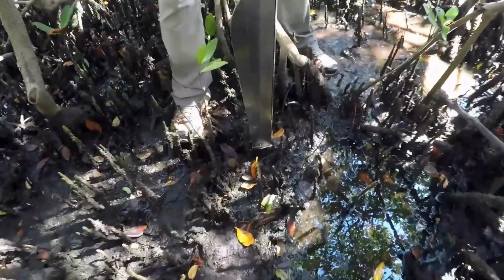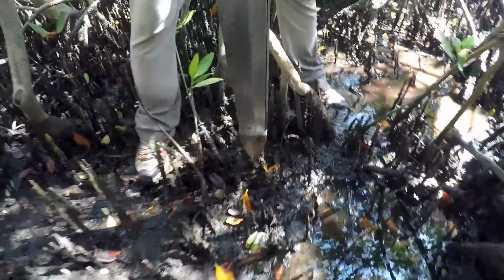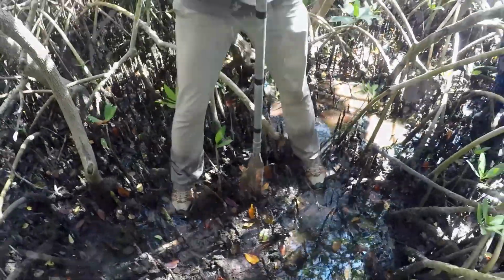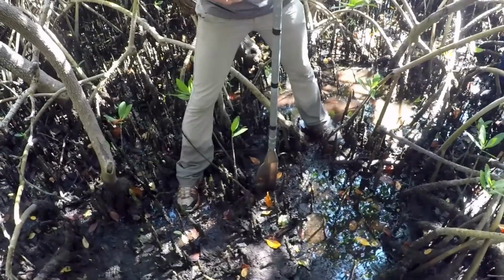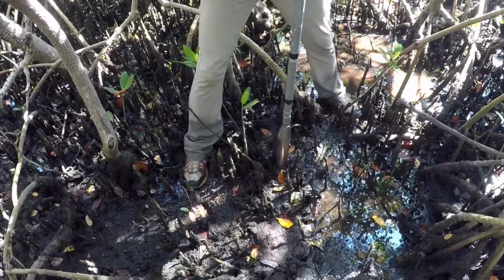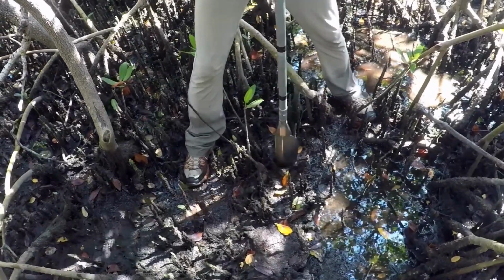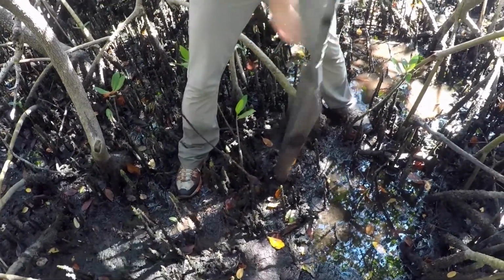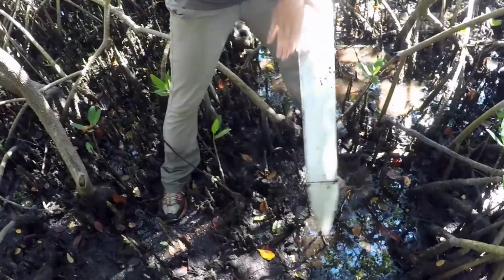Feldspar plots should be cored every 6 to 12 months in order to gauge sediment deposition using a coring device with minimal compaction, such as a Russian-style peat corer. Cryogenic coring devices also have minimal compaction. In this method, liquid nitrogen or dry ice is used to freeze the sediment before the core is drawn up out of the ground.